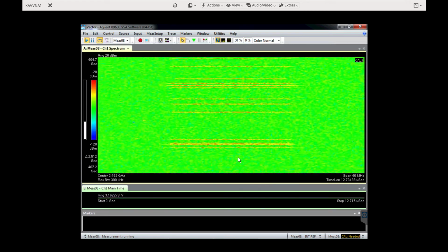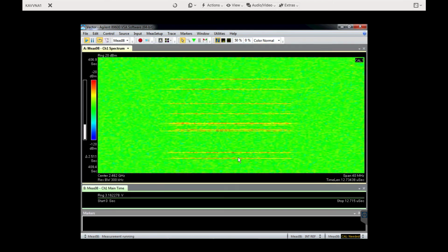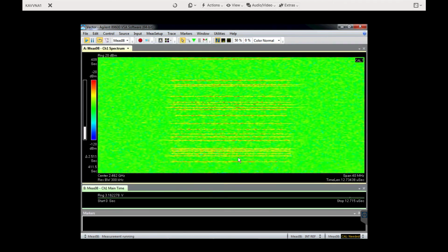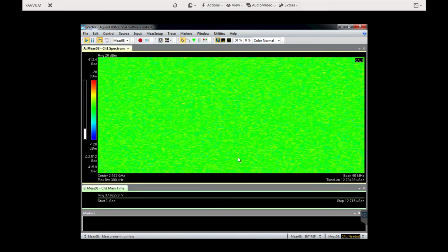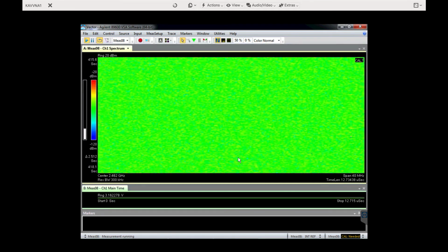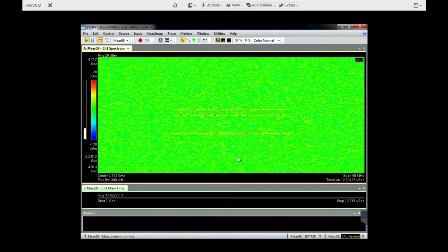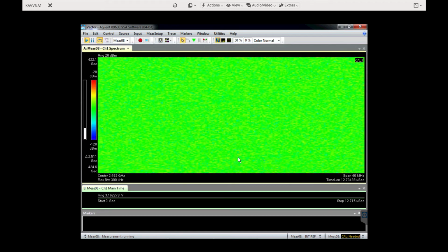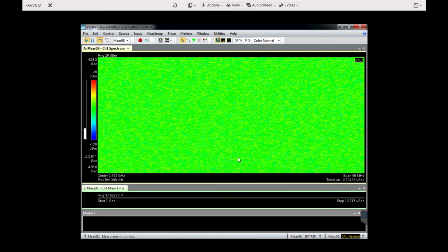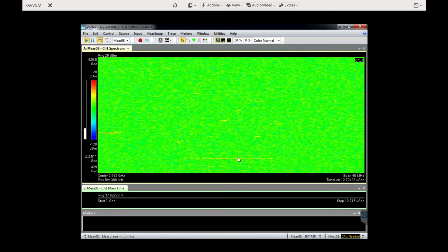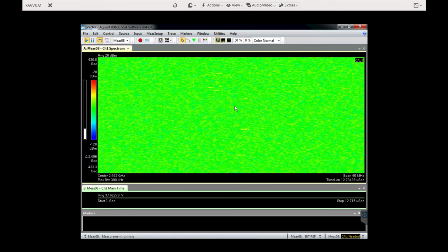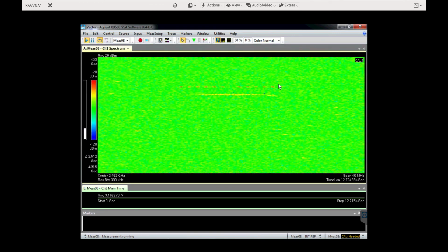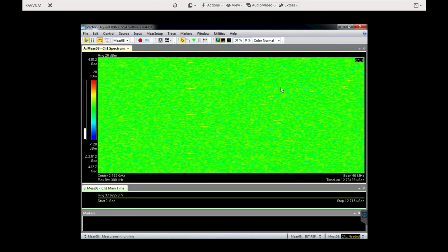Now, as we said, Bluetooth also operates in the same band. So let me stop this speed test first. And I have a Bluetooth speaker close to the VSA and connected to the same mobile device. I will play some files so data will be transferred to that Bluetooth speaker. So let me start. Bluetooth uses frequency hopping. As we see, these hops correspond to the Bluetooth packets.